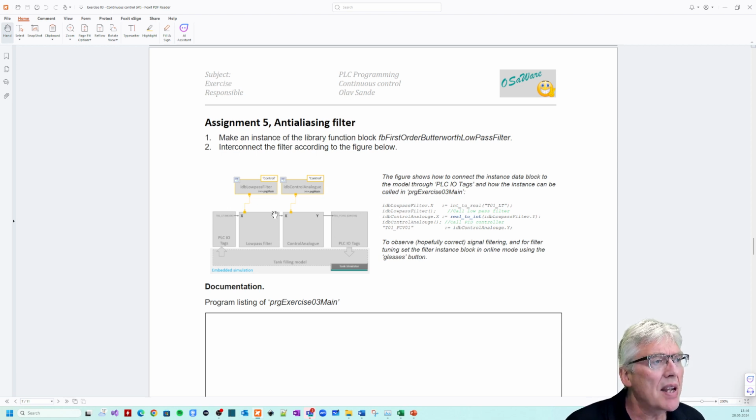And of course, there's no tag connection here between the filter, because now the filter would have to get this raw value, because they're not scaled. This low-pass filter works with any value, but then you would have to convert it, like indicated over here. So you get an integer value in this tag, and maybe you would have to convert it, or maybe you should convert it. This conversion is pretty implicit, but we use explicit casting if we can.